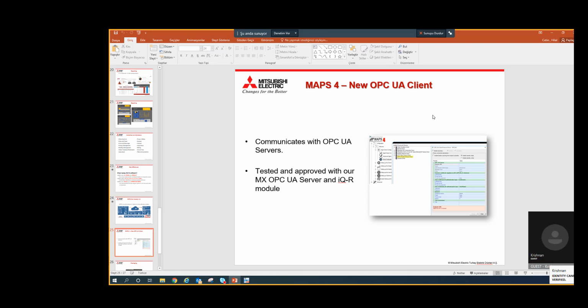So for my simple understanding, if I select 300 scan points, then I have 300 scan points to communicate with different PLCs, and internally it will have 300 scan points to communicate with the image and pictorial representation, that is the MAPS server. That also will by default have 300 scan points, is it?